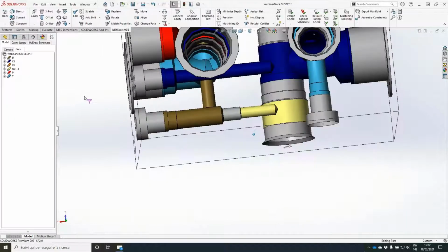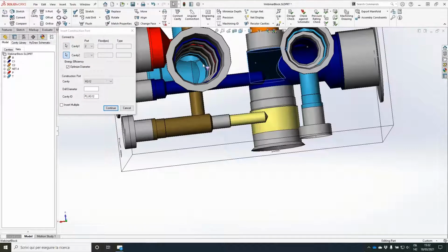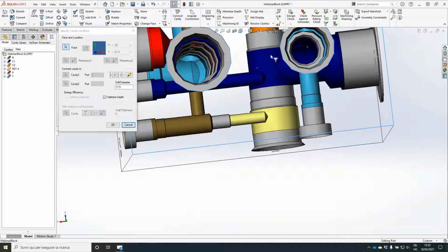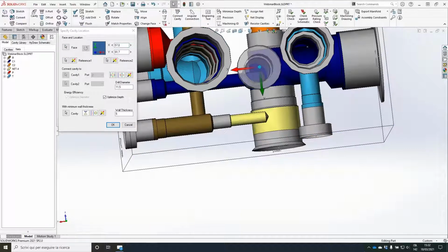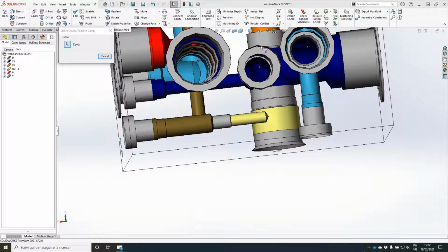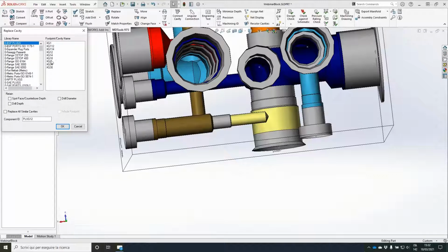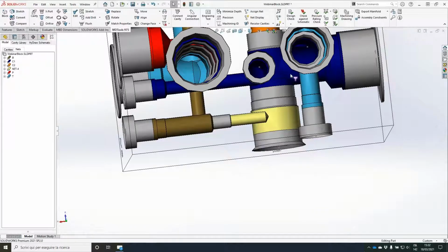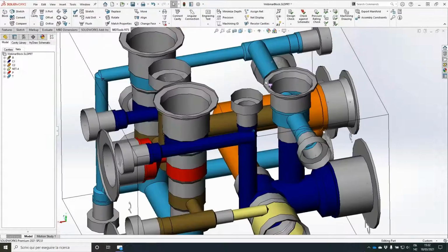Here, and now we have room for a connection on top here. Let's say 1x4 here. 1x4 is too big. We will replace the cavity with a 1x8. So we can do a replace of this cavity, and we can go to the BSP plug 1x8 drill depth. So we keep the same drill depth. Now we have made that connection.